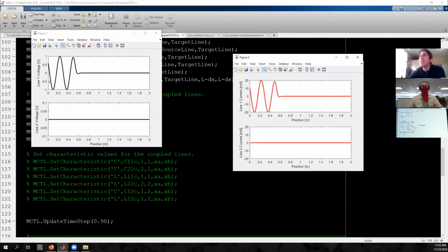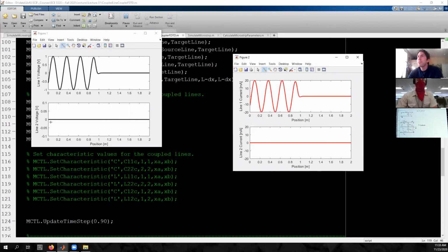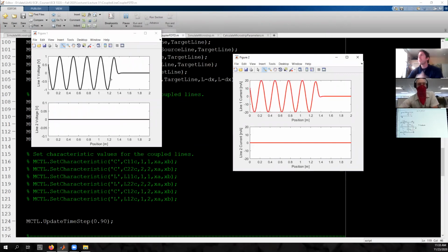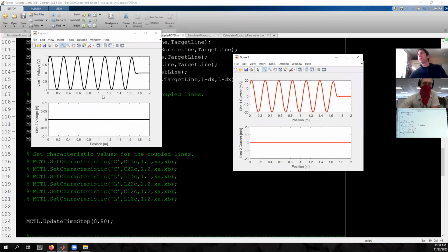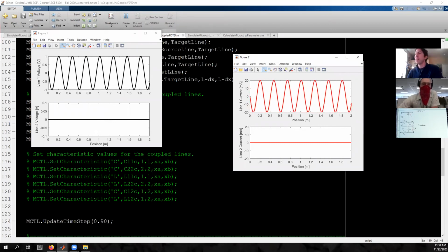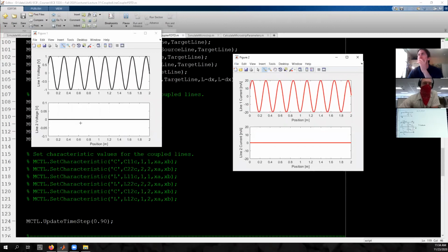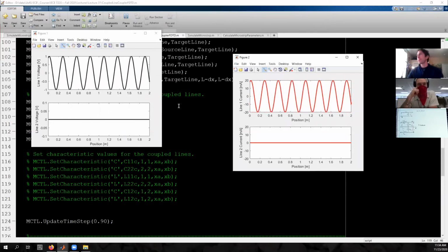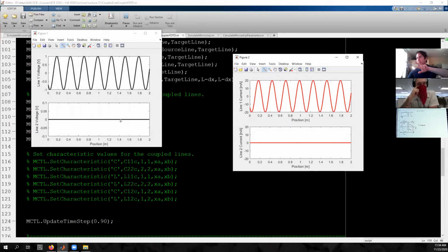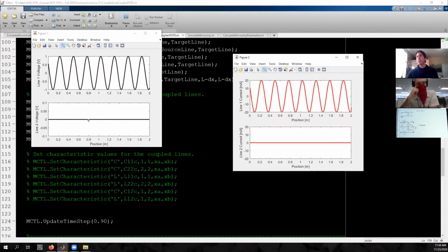So you notice you have a signal line here and a reference. I'm just exciting the one here, and right now they're isolated, so there's no crosstalk between them. It turns out it's really hard to get a good model of crosstalk without kind of blowing up your simulation. So what you need to do then is fill in those matrix elements to get the crosstalk between them.